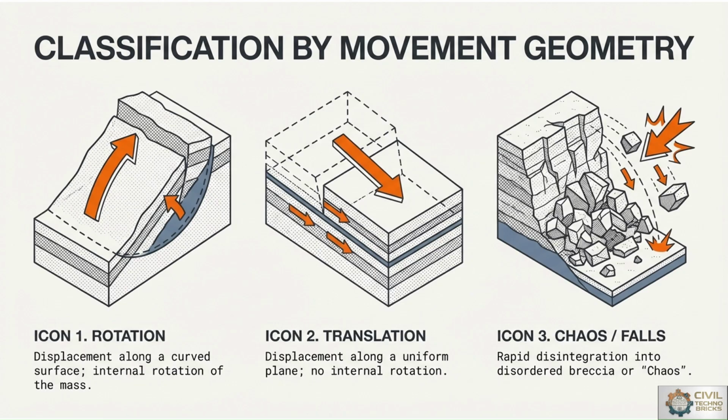In a rotational hazard, static geological lines on opposite sides of a slip fault are no longer parallel after a failure event occurs. The movement behaves around a distinct center of rotation situated within the fault plane. This creates a concave scoop-like break within the hillside. The field identification relies on tracking a series of step-like blocks that visibly tilt backward into the slope in the rotation phase.